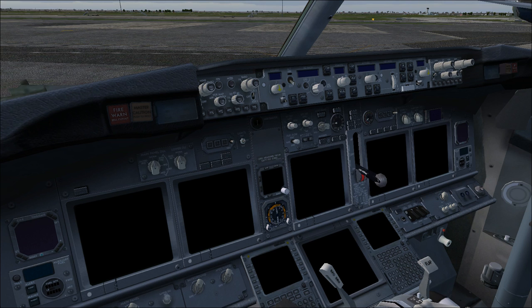The screens work on AC power. They can be powered by DC power, by the standby power on board the aircraft. I will not go inside the electrical system today, so I will not give you any details about how they are connected to the system. Just remember that there is the possibility to check all the screens using only DC power, so power coming from the batteries, while the ISFD and the standby instrument power is DC power, the hot battery bus, and so it can be powered only by the batteries.